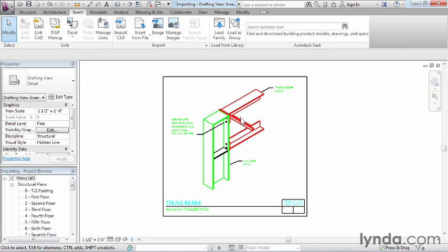The other thing that's going to be bad about this, if you do an explode, is it automatically doubles the size of the original detail that you brought into Revit. So if this has been a 0.5 meg detail and you explode it, it suddenly becomes a 1 meg detail inside of Revit. If you only have one, it's not a big deal. But if you have 50 of them or 100 of them and you bring them all into Revit at the same time, suddenly instead of having 50 megs worth of information, you might have 100 megs worth of information inside of your Revit file. And if you do that, it's going to make your drawing file less stable.